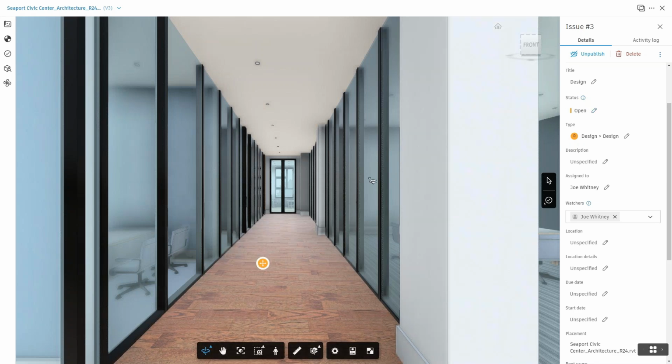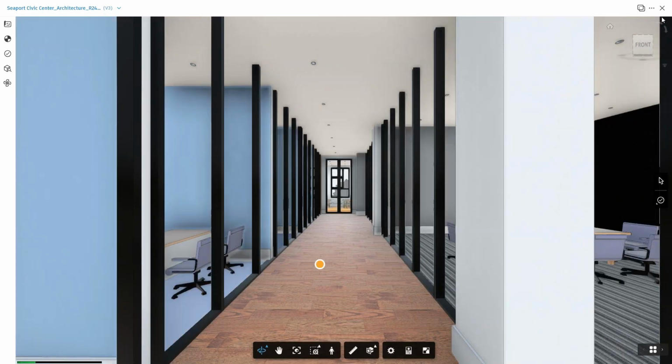And when you click on it in Revit, if this is the view I was looking at whenever I was placing this issue node and adding all this information, there's a little view placer inside of Revit. What that does is it takes them to the direct view and the direct positioning whenever you place that markup. That way, whatever you're seeing in the file, the designer is seeing the exact same placement. So awesome coordination tool, super powerful, super versatile.